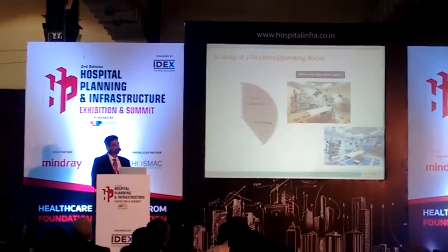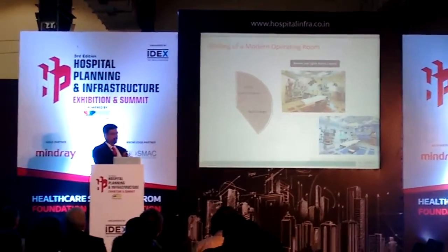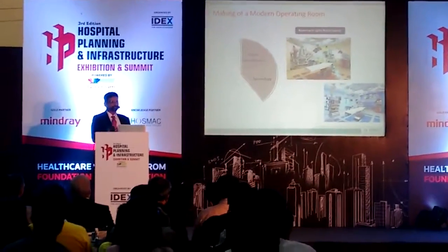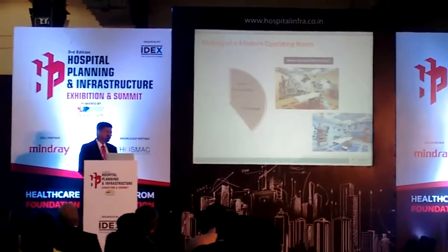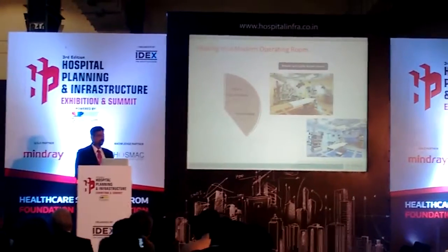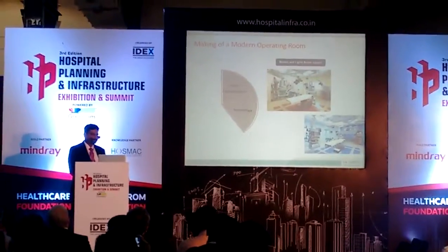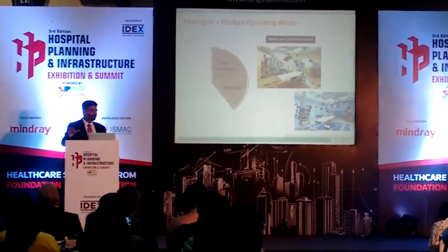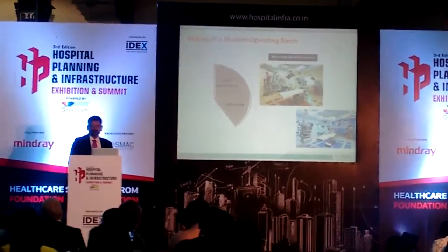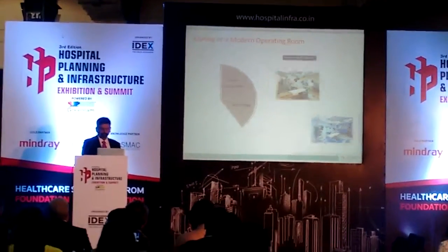And contamination through air is only around 25 to 30%. The rest is the personnel working in the theatre, and the cleanliness of the theatre. So laminar is not necessary, but definitely air filtered with terminal HEPA filters, which can supply onto or right onto the table, is good enough from the point of infection control for an operation.